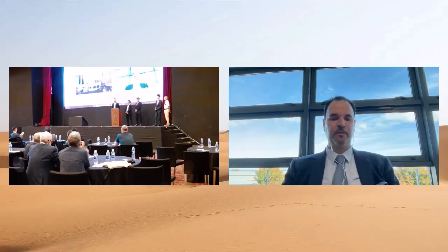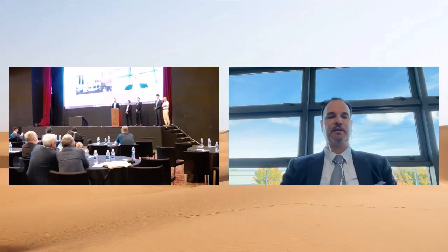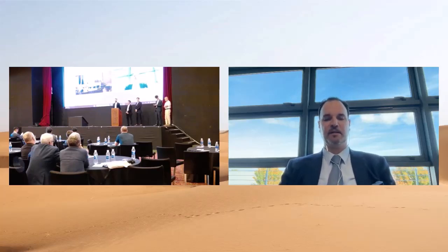So that's one of the purposes of the BCF topics and how those topics are signed off and approved. There's also a heat map in the repositioning of objects, and only real advanced users would use this heat map in this way. But it's the absolute heat map where the middle range would show you how to correctly position that object. And we have an algorithm that in the future will automatically reposition these objects for that perfect fit. But again, to answer your question, the validation of an object within tolerance that is found, its correspondence, is a human one. And that decision is made and sent and approved via BCF.